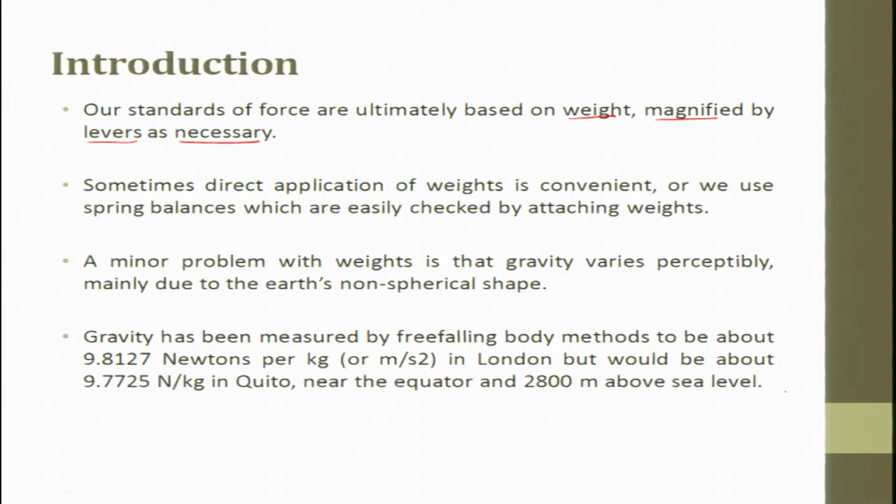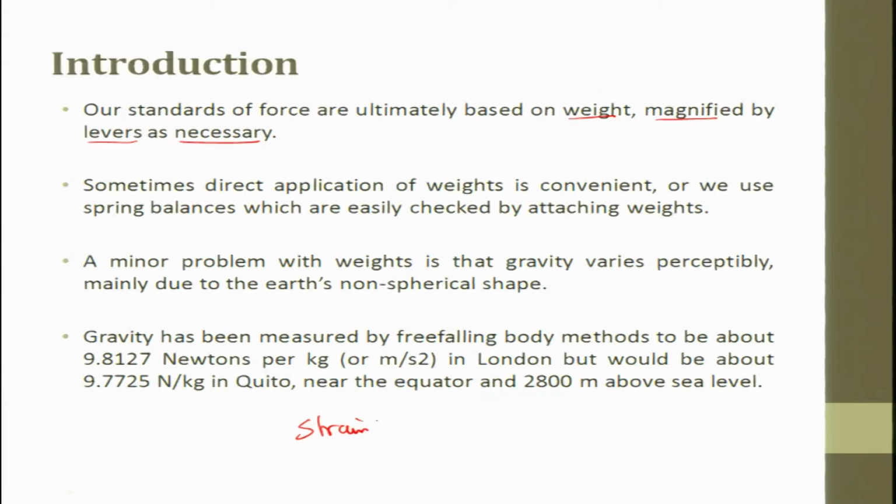In a spring balance you put a mass, and the moment you put a mass, the spring gets stretched. How much it has stretched is nothing but your displacement. From the displacement you find out strain, and by the way, what is the definition of strain? Strain is nothing but dl by L, where dl is the increase by applying the load.